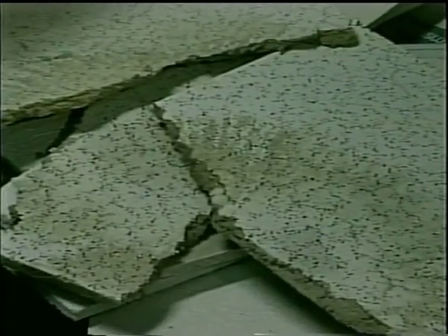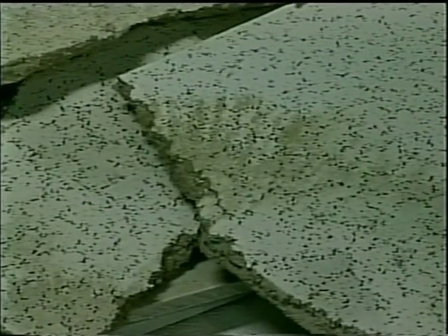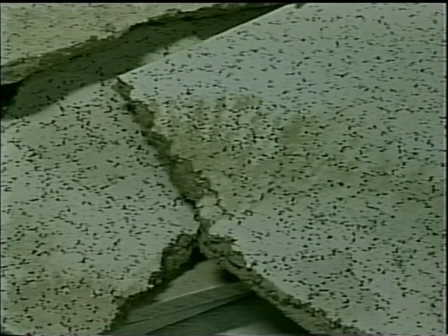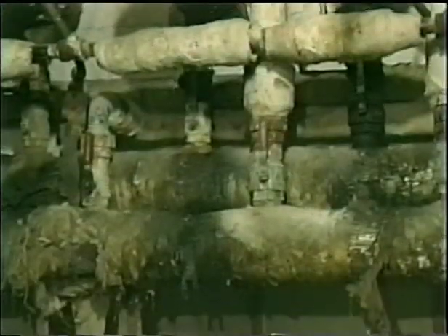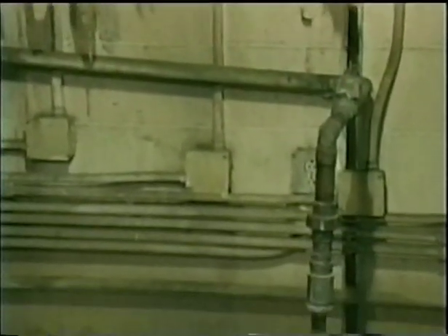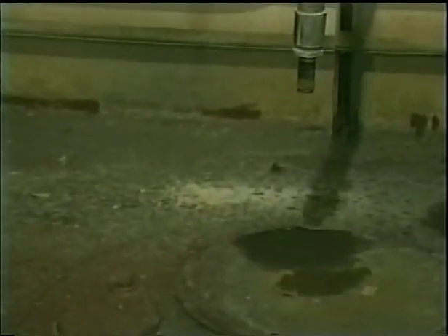One of the most common types of damage to building materials is water damage. Leaks in roofs or pipes or floods from plugged drains are all common problems. When water gets into asbestos-containing materials, it may break down the compounds that hold the material together, causing it to be more friable than it was before it got wet. It may also completely destroy the matrix of the material, leaving asbestos exposed, or on the floor, or in the water that damaged the material. Once the asbestos is released from its adhesive materials, it is able to become airborne.